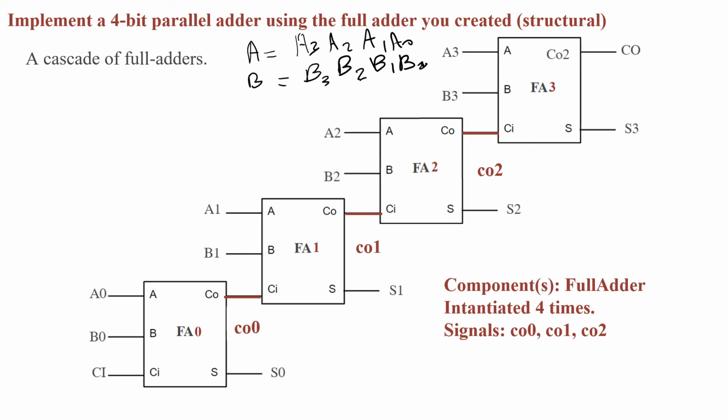Notice how A and B each have one name, but for example A has multiple bits. So variable A is a cable consisting of 4 unique wires. So A is a 4-bit variable, and the bits of A are A0, A1, A2, A3, A0 being the least significant bit.